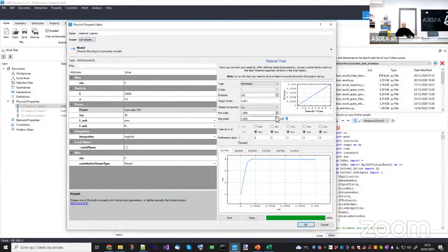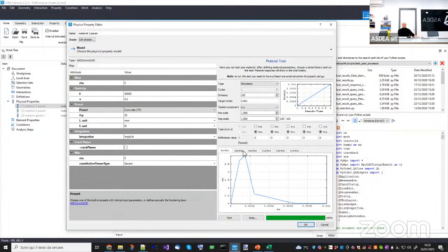Like for example, if I want to use a mesh size of 300 millimeters, the G that is here, which is basically the equation that I showed you before, will be regularized using this characteristic length. And this is actually how it will look like inside a material, inside a finite element which has this dimension, okay?